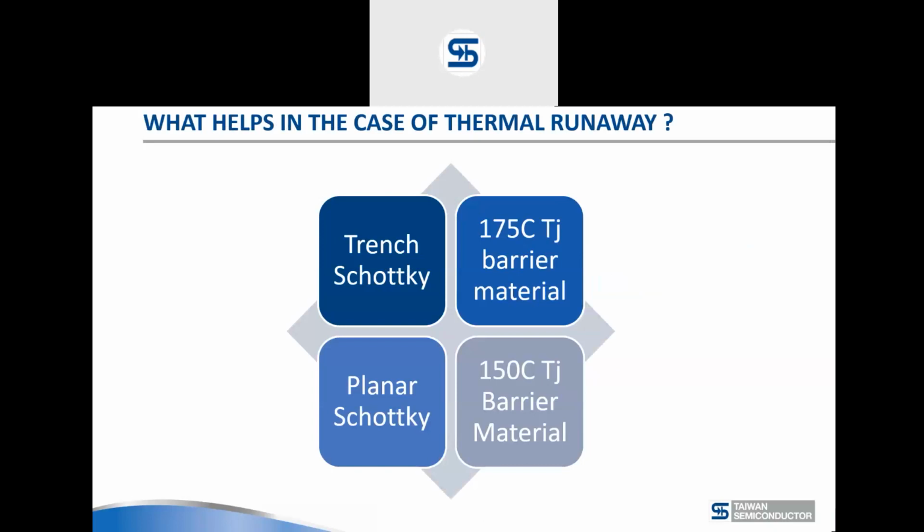But under the right conditions, also planar Schottky diodes or 150 degrees C rated junction barrier materials will not go into thermal runaway. It's just, if you are really pushing the technology to the limit, then that's what you want: trench Schottky and 175 degrees C rated diodes.